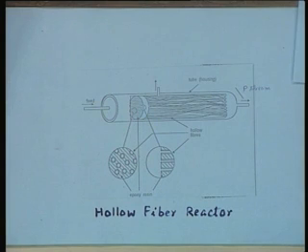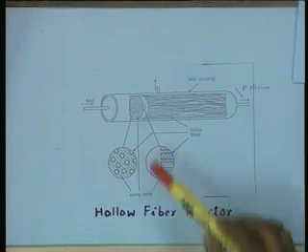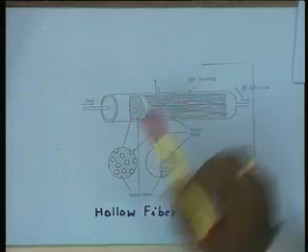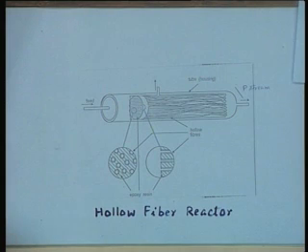The center, is it the fluid flowing? Pardon? The center, is it the fluid flowing? No, in the tubes, in the hollow fiber capillary tubes the enzyme is contained, and in the annular space provided between the tubes and the shell the substrate feed is fed into it.